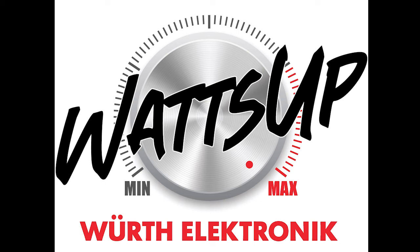Next, we'll discuss the LC filter. Now, an LC filter at the DC converter output is recommended if a low noise output voltage is required. For our seventh design tip, we recommend selecting a cutoff frequency at 1/10 of the switching regulator frequency, and then selecting the output capacitor, for example, 22 microfarad, and finally calculating the inductance. Our equation turns out to be the inductance equals 1 divided by 2 times pi times the switching frequency, all squared, times the capacitance. And our eighth and final design tip is about the ripple measurements.